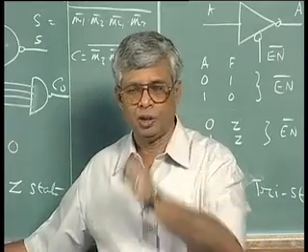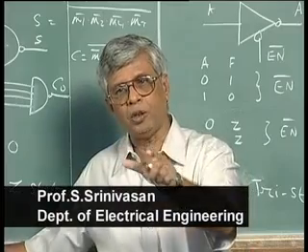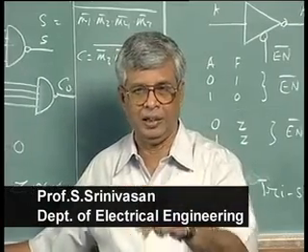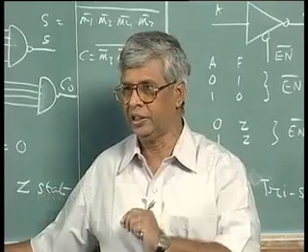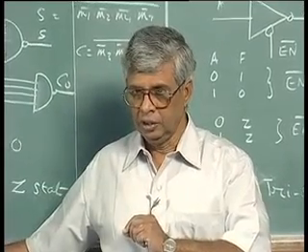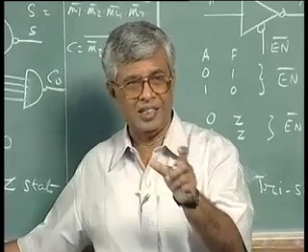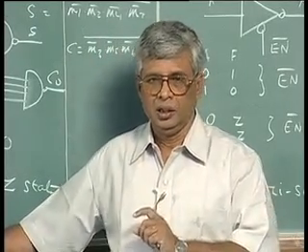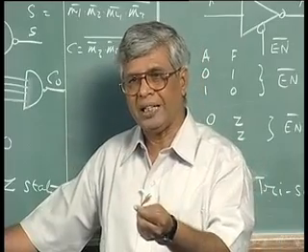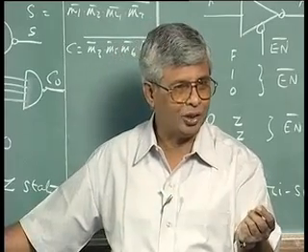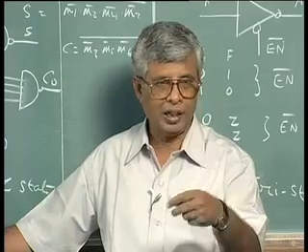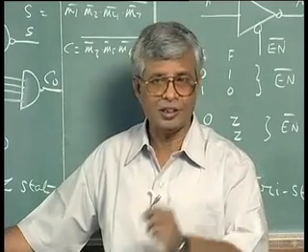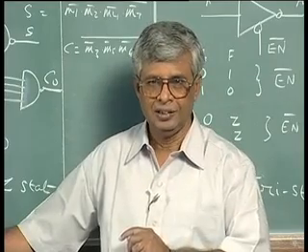So functionally there can be the same things a small scale integrated circuit can do, but putting them together becomes an MSI. The same way a counter can be, a register can be an MSI, even though a flip flop will be a small scale integrated circuit because it only has a couple of gates, at most 4 or 5 gates including the clock. When you put flip flops together to make a register, a 4-bit register, a 4-bit counter, they become MSIs. So we have now used MSIs without our knowledge. 4-bit full adders we have used in our design, adder subtractors and that type of thing. We are talking about counters and registers, shift registers. These are all MSI circuits. They are also MSI based design.